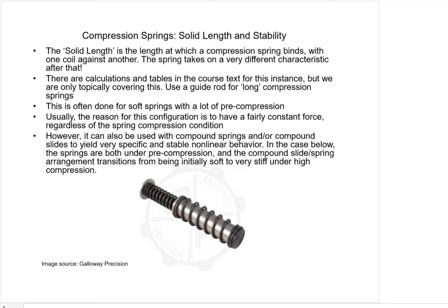Compression springs, these are also helical coil springs, can also be compression springs. That's what we're talking about with the solid length. Here it's defined, one coil against the other in this first bullet here. Obviously this spring takes on a very different characteristic at the solid length.